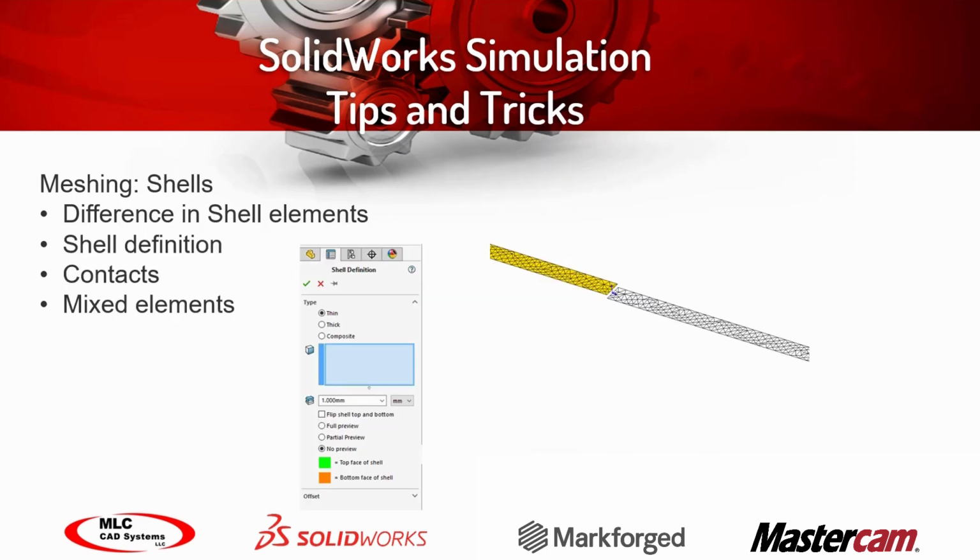Shells: the easiest way to define or take advantage of shell elements is by modeling the part using sheet metal. The second way that we recommend to define shells is by using a mid-surface, or you can manually define the shells by a defined face, right?